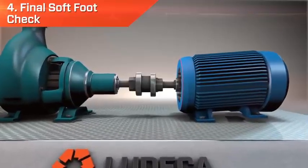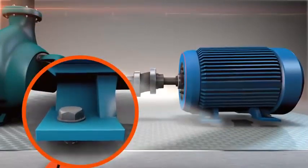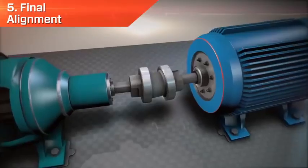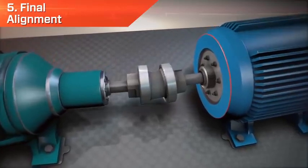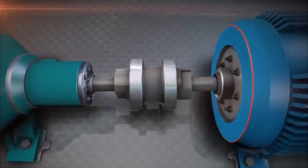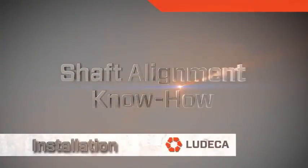In the fourth step, we diagnose and correct soft foot with the assistance of the laser system. Aim to have all soft foot readings within 0.02. Finally, in the fifth and last step, we measure the alignment, make corrections, and achieve the final alignment to any required targets within tolerances.